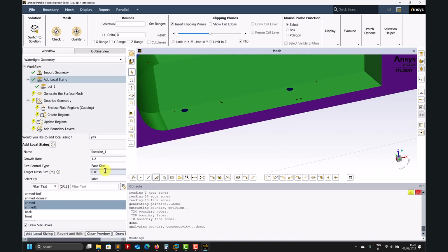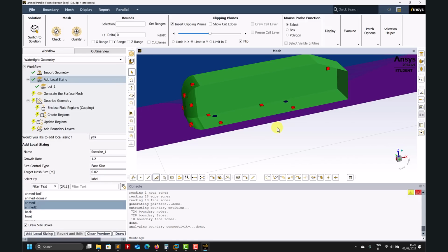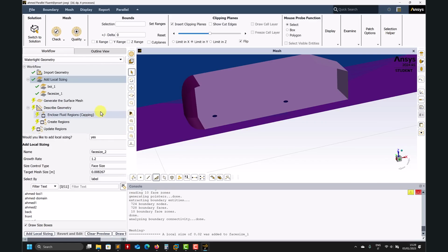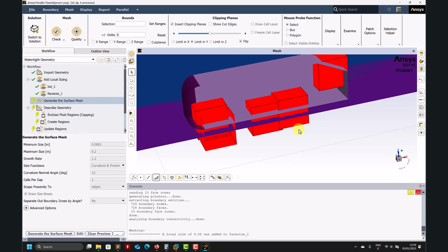Now here I'm thinking about the maximum memory, or maximum number of cells, that I can use. Now that will be too large. So let me use this one, because when I generate the boundary layer, I think we will get non-orthogonality problems, and then I will show you that as you refine there, you solve the problem, similar to snappyHexMesh. So the same problems that you have there, you will have here. Probably here it's easier to control. There you go. Generate, and we should have a mesh very soon.